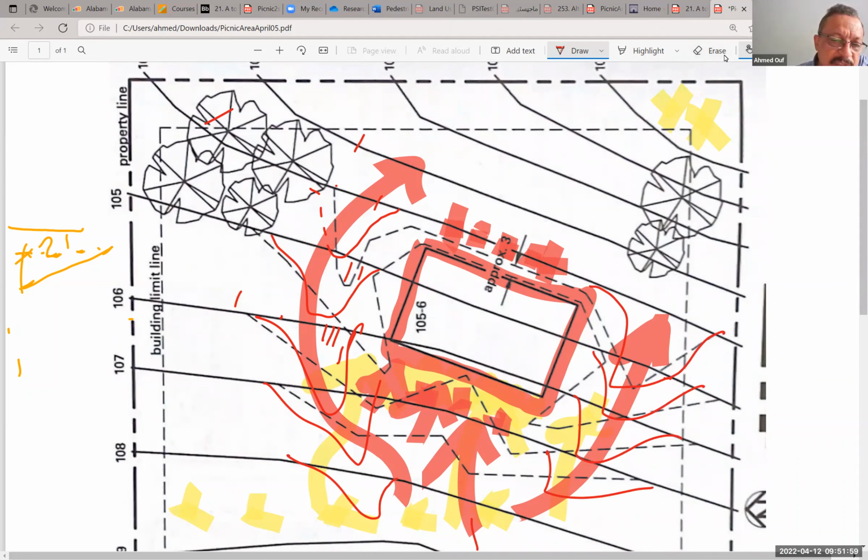So actually when water comes here, instead of going to the back of the building, it will start going like that. So actually I'm making a depression. I'm creating an area. This is still a cut area, as I said before. Cut area, I was just drawing the arrow the wrong way. So the water will start to go around the building.